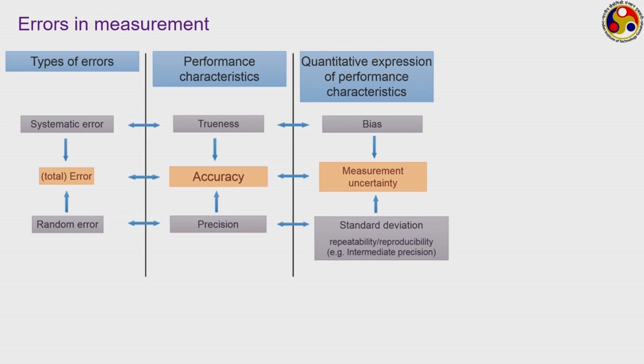One is systematic error, which generally is associated with very common terms like zero bias error, zero drift, sensitivity drift, etc. Measurement errors can be quantified. We can easily identify their source, and therefore, via the process of calibration, we generally can eradicate or at least minimize the amount of systematic error from a final measurement.